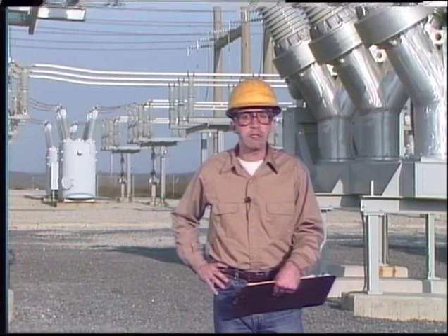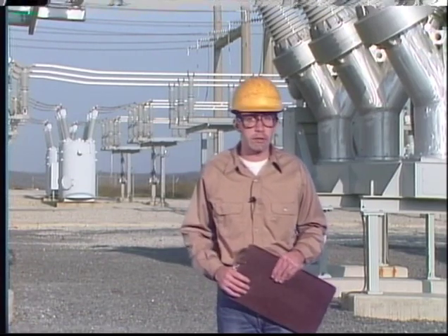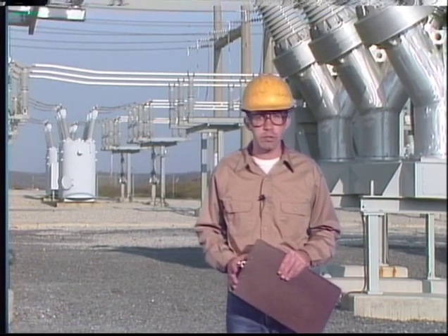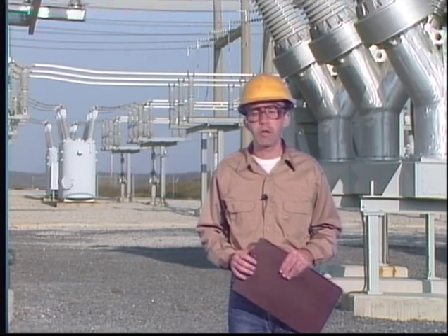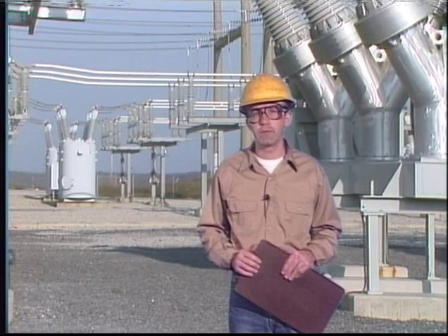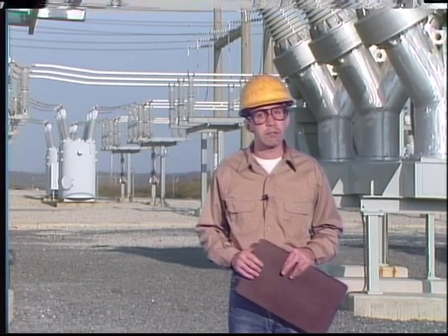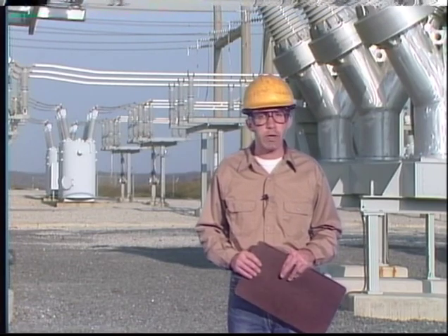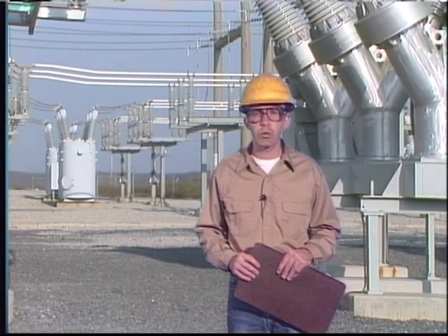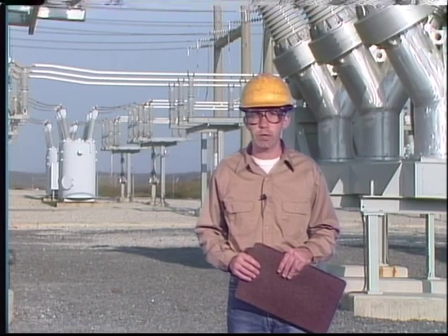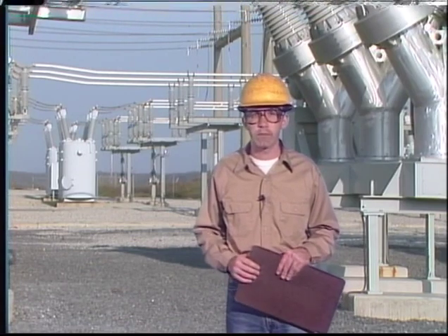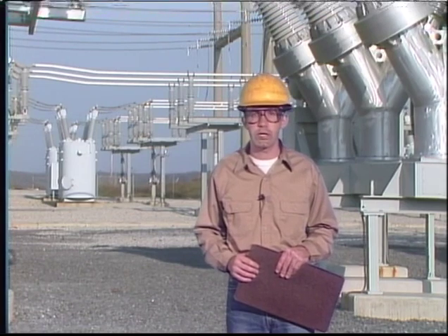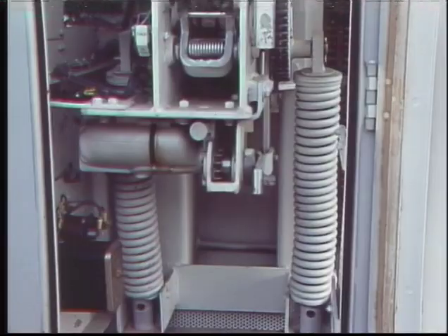After a breaker has been de-energized, isolated, and grounded, its control circuits have been de-energized, and all appropriate switches and circuits have been tagged, the breaker is electrically safe to work on. However, it's not mechanically safe until it's isolated from its operating mechanism. Most operating mechanisms have some form of stored energy that can trip or close a breaker even without control power. All that's needed is for a latch to move to release the stored energy and operate the mechanism.